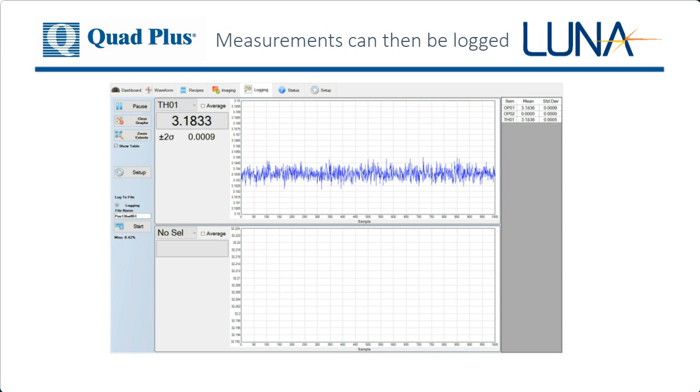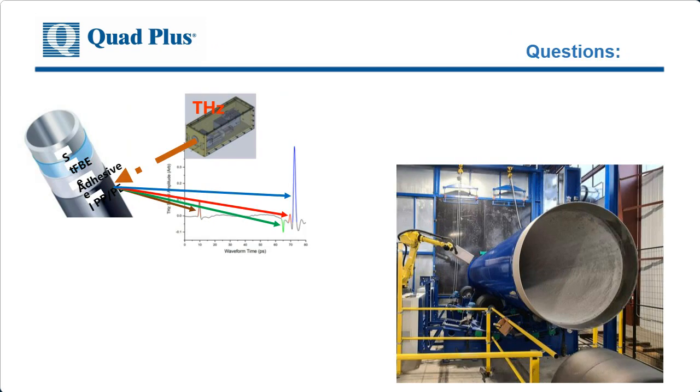How can we verify the calibration of the system? So typically what we would do here is the customer can provide a standard sample. The standard sample will be mounted in a known location that the robot knows about. It's actually a sample holder. And operations at any point in time can move the robot to that sample position and verify the thickness of that standard sample. There's also ways that we can do continuous online verification of the system as well. Earl, can you talk about that a little bit? About adding possibly a fused quartz sample into the system for continuous testing?